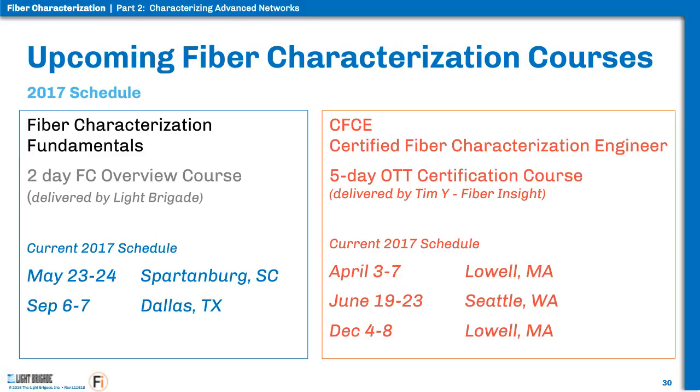The really cool thing about all the different tests that you perform is that some of the tests can help other tests to clarify what's going on. So if you look at the CD result and then you also look at the OTDR result, if you have mixed fiber types, it will show up on the OTDR as apparent gainers, a dissimilar fiber transition.